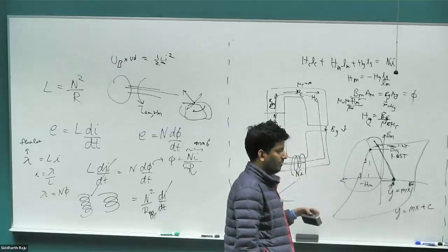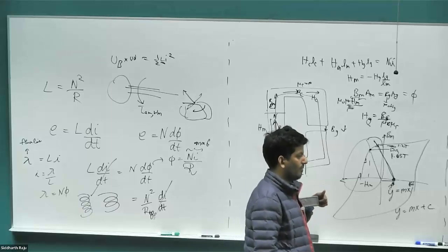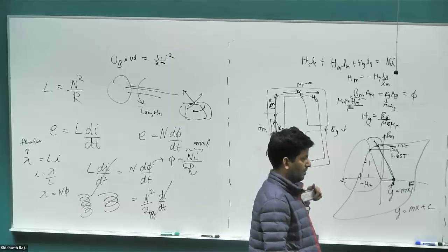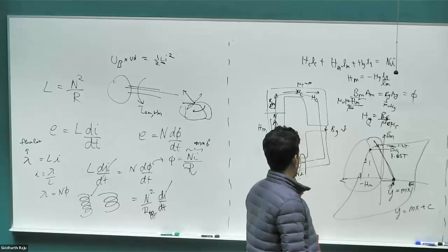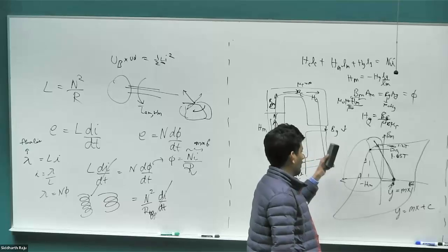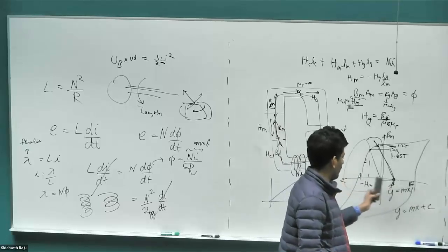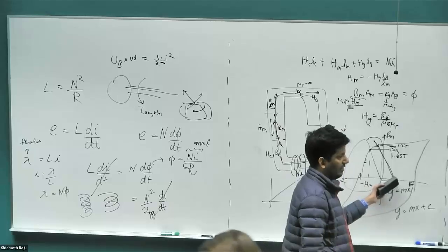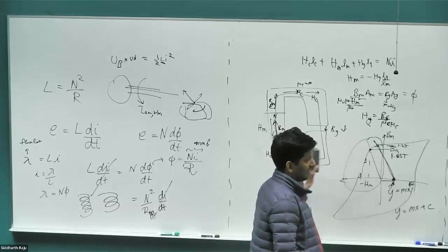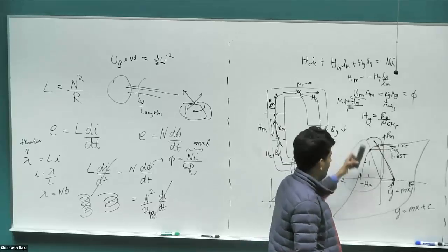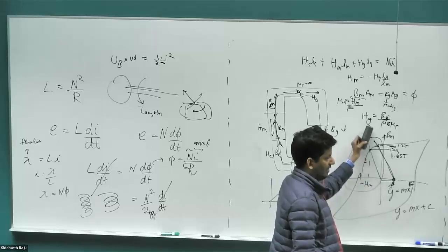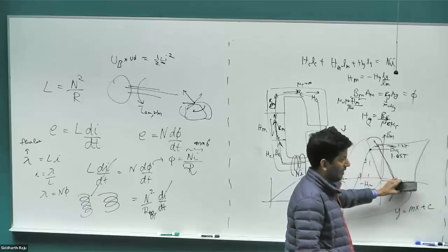It'd also be really complicated, right? Because the magnetic field from the coil would affect the effective mu r, right? No. When we are looking at the magnet, we are not going to talk about mu r at all. There is another problem. You don't get any advantage because the way I've drawn it, it looks as the amount of Ni you need is very tiny. But if you remember from the BH curve of a neodymium magnet, it's about 900 kiloampere per meter where the coercivity is. Towards the top point, let's say you're already at 1.05 Tesla. To go from 1.05 Tesla to 1.1 Tesla, to push the magnet in the direction, you'd have to put so much current in the other coil that would just not make sense.